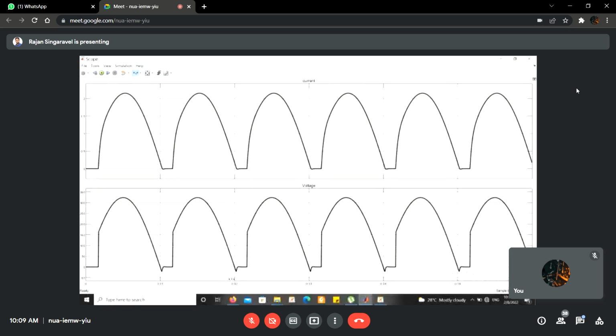When negative voltage is introduced and you take the average, definitely the average voltage is going to be reduced. This is the concept of dealing with the R load, which is a full wave rectifier. When RL is the load, then for the same firing angle, the average output voltage will be lesser than the previous one.